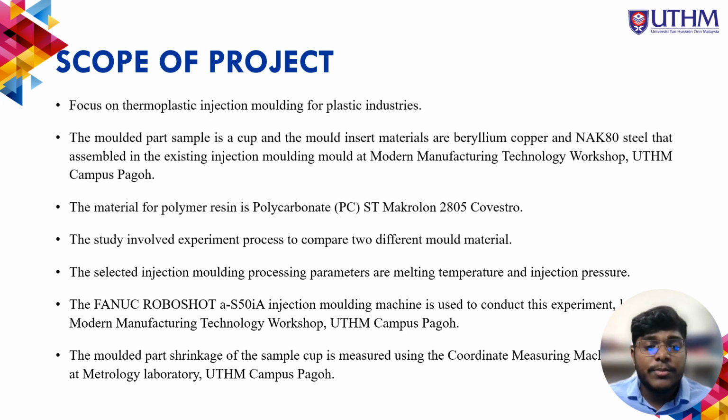The study involved an experiment process to compare two different mold materials. The selected injection molding processing parameters are melting temperature and injection pressure. The Fanuc S50iA injection molding machine is used to conduct this experiment. This injection molding machine is in the Modern Manufacturing Technology Workshop at UTHM campus Pagoh. The molded part shrinkage of the sample cup is measured using the CMM, which is the coordinate measuring machine, at the metrology lab.